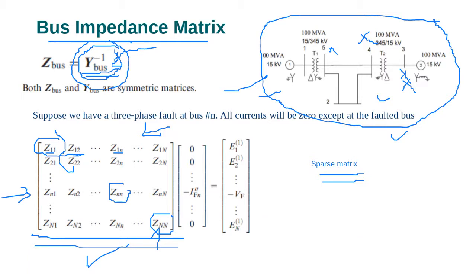And every time you need to calculate the parallel, the series, etc., and maybe convert from delta to Y. But look at here. Now we can find the Thevenin impedance. What does it mean, Thevenin impedance? It is the total impedance looking from bus number 1.